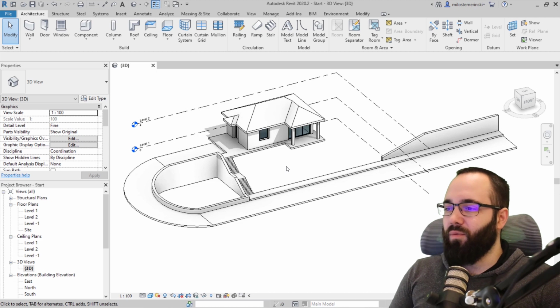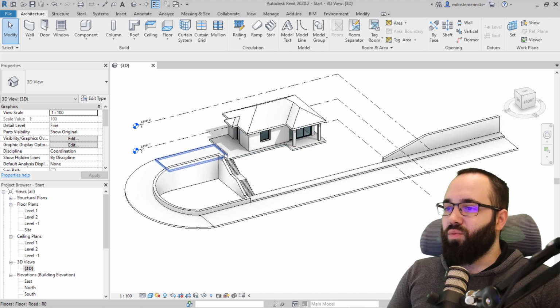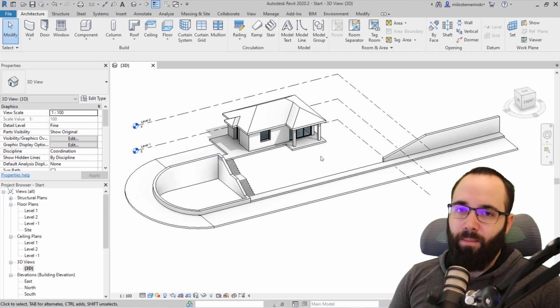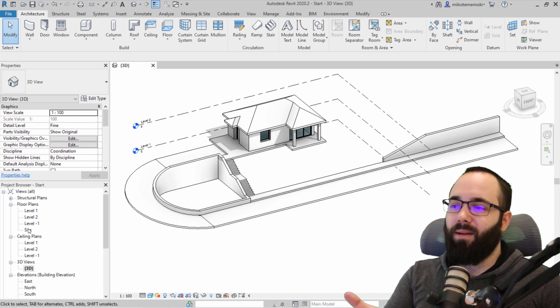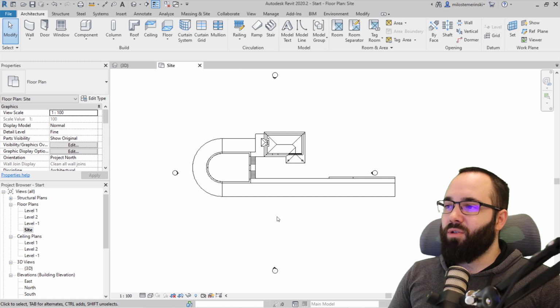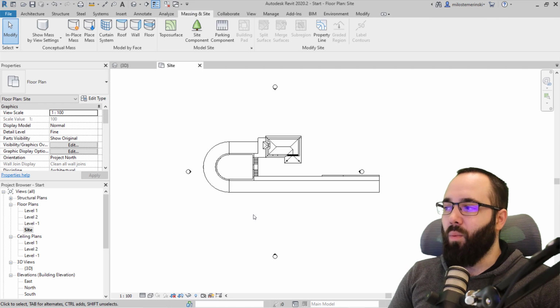So what you want to do first is move to the site plan here. There we go. Once we're at the site plan, usually I just like to generate a surface which isn't going to be fitting in perfectly, but we have a starting point. So you're just going to throw it out there and then you start adapting it. So what I'm going to do is go here to Topo Surface, go to Place Point, and usually what I like to do is just place one point first. So just one point like that.